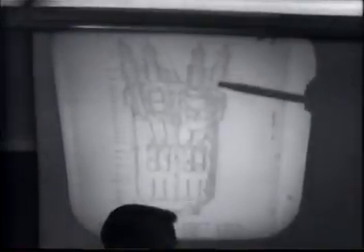And this gets kind of crowded, but it performs the same function. As you can see, we have a single tank diameter, I don't have the figure handy, but it's in the order of 3.5 to 5 feet, depending upon the manufacturer, in which we have all 6 bushings around the perimeter of the top of the tank. Then we have a contact mechanism for each phase in the same tank.